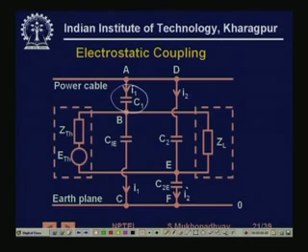So now you can understand that especially if the ratios C1 to C1e and C2 to C2e are different, then you are going to have a good amount of voltage induced, and especially if this voltage is AC, then current will tend to flow through these capacitances, and naturally at the capacitor divider point some voltage will be induced. So this is the phenomenon of capacitive coupling, through which a high voltage conductor can induce noise voltages into your circuit.